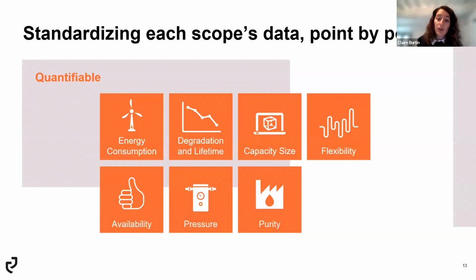And for that, you need to know if you can switch off all of your electrolyzers except 50 megawatt worth of capacity, or if it's better for your operation to just reduce the load of all your electrolyzers down to, I don't know, 5%, 10%, whichever fits to make it up to 50 megawatt.